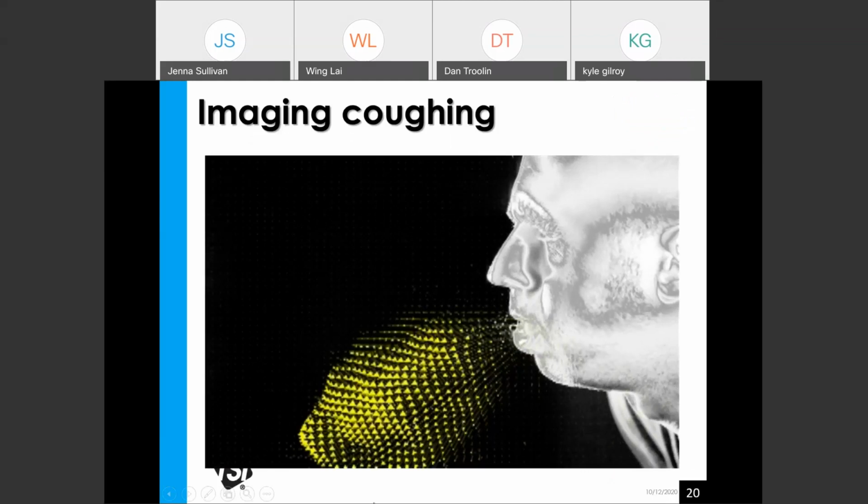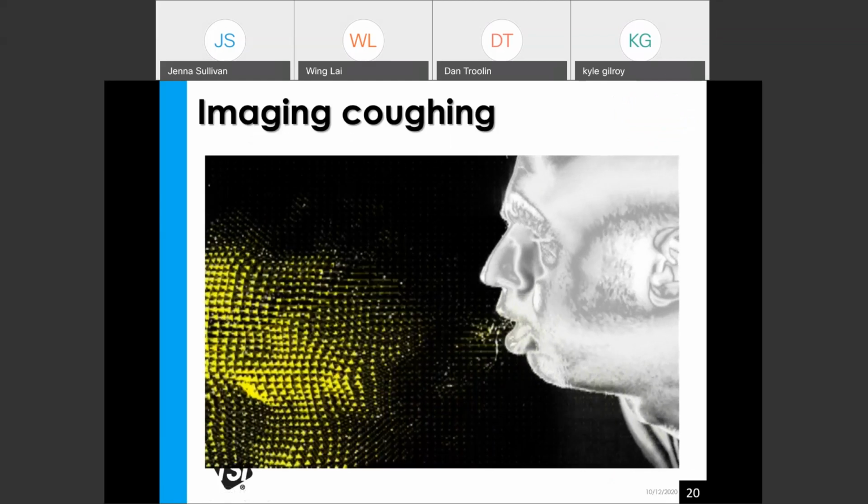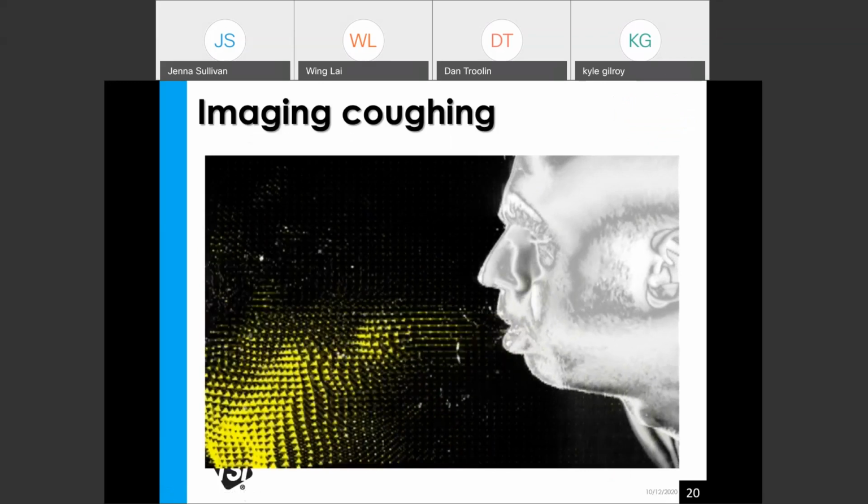These are generated from the previous image. Using cross correlation techniques, we are able to get the velocity vector fields based on the droplet motions that you see on the previous slide. Again, you can see the power of cross correlation techniques, which let us get quantitative results showing the vector fields of the same image captured a little bit earlier.